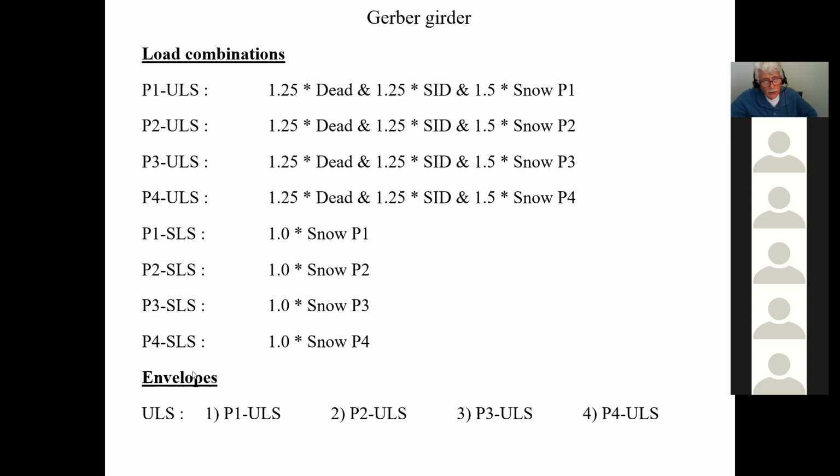Then after that, you're going to do the same thing for serviceability so that you can look at all the deflections, okay? I personally, for serviceability, like to look at each one individually to see how each one is creating, because under the envelope it doesn't give you that, but at least you'll get an overall view. But the serviceability is not important. As far as strength goes, this is good, I like this. But this here is not necessary, but if you want, you can create that also. So these are all your load combinations.